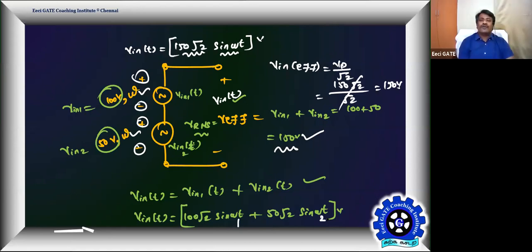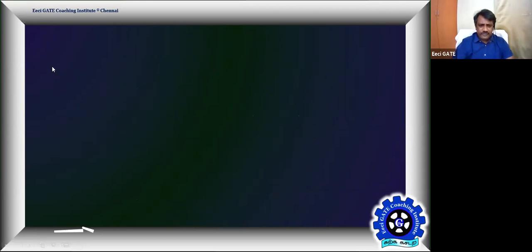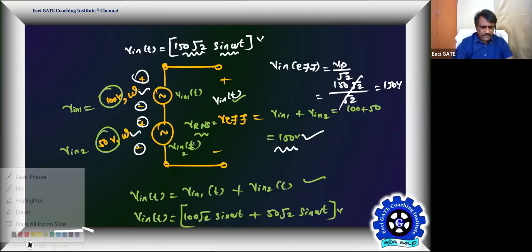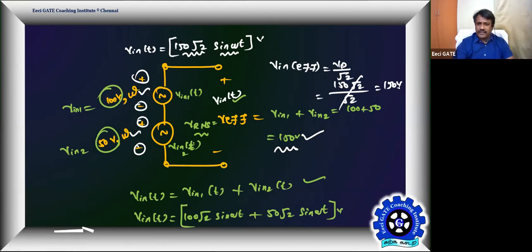We should know so many facts only under a condition. Yes, the condition must be known first. So this is valid. You can just add the RMS values of two AC sources connected in series, provided they are in series aiding, and provided they have identical frequencies, then you are free to add them or subtract depending on aiding or opposition. Getting, everyone? Getting, all of you? Following, right? Yes, sir.